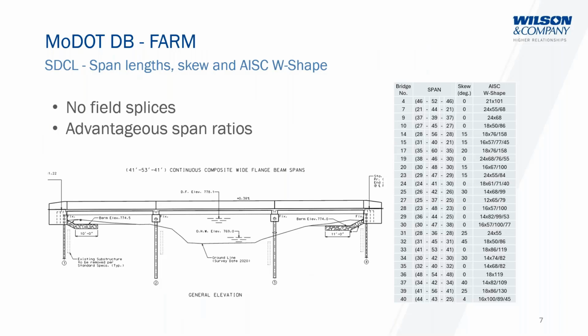I will mention that bridge 40 was on a curve and it was super elevated. All we ultimately did was widen that bridge a little over a foot and then stripe it for the curve. So we didn't have kinked girders or anything like that. We didn't venture down that road, but there was an opportunity to probably do so. Instead, the contractor elected to just make it a little bit wider.